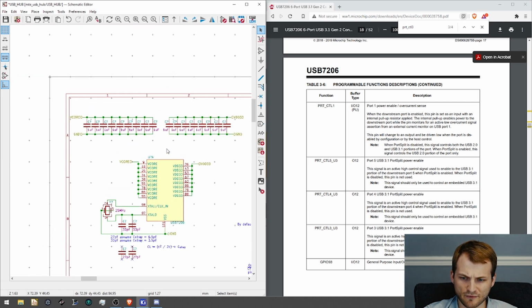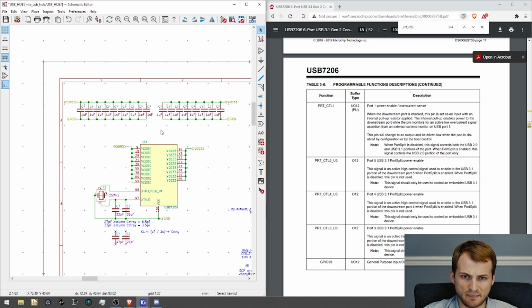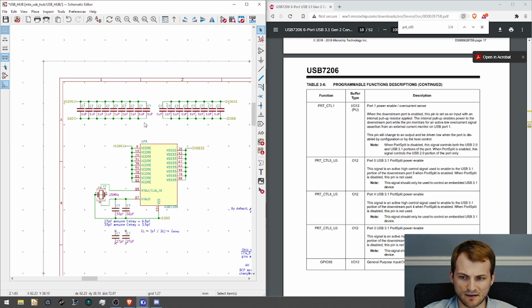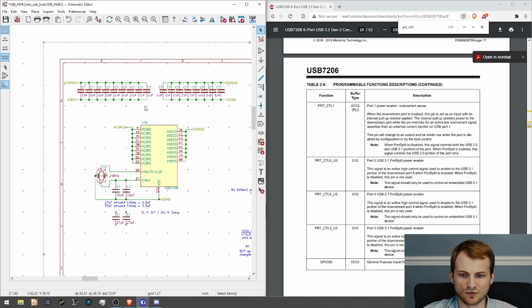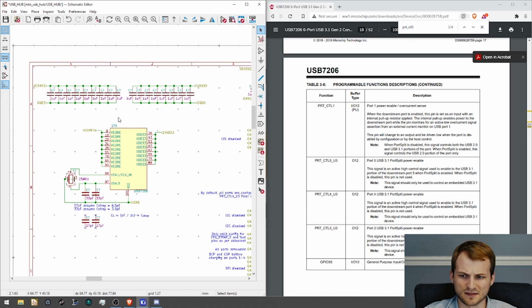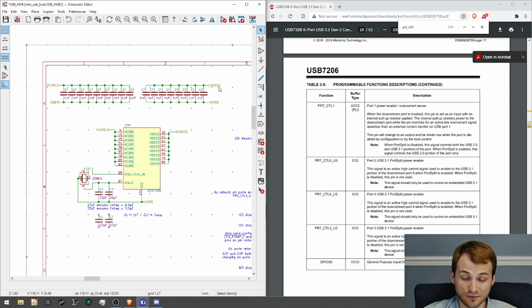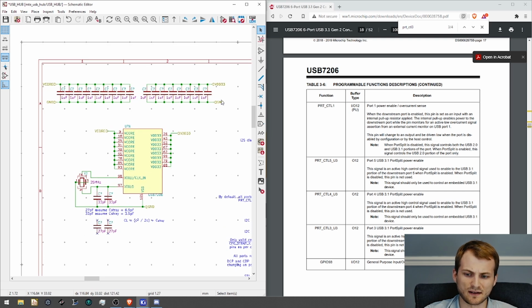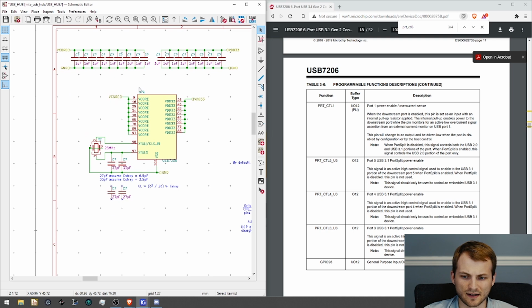This, and I mentioned before, is one of the only bigger high-speed ICs that I've ever seen that only has a single ground pad, and it's the thermal pad, which will make the layout kind of, I guess, interesting or just kind of neat to mess with because I've never done that before. But every one of the VCC pins or the VDD33 pins and the V core needed decoupling. And when we're working on the layout, probably we'll add a local bulk bypass cap for each one of these as well, but we'll see how the layout ends up.